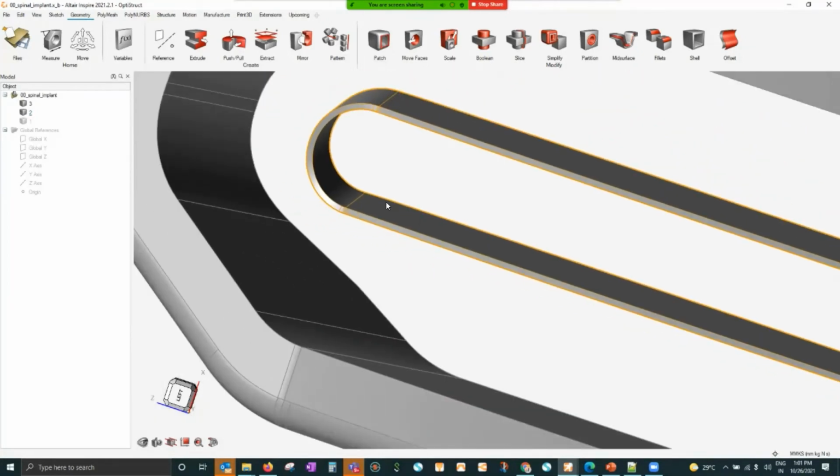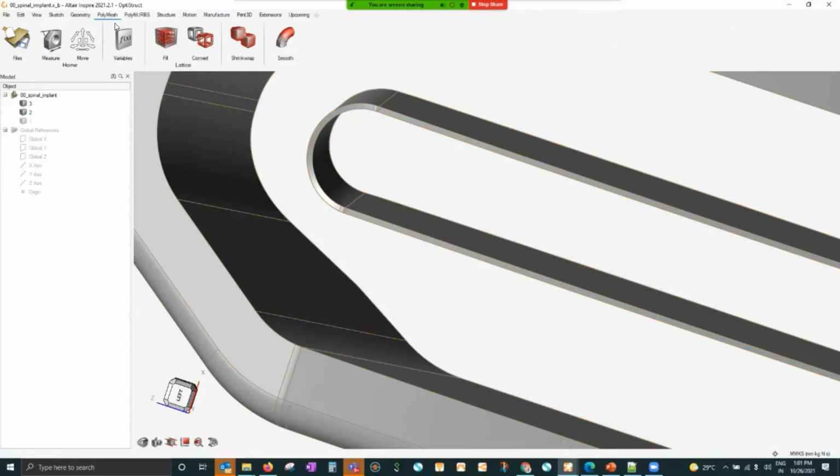That is number one. Number two is, if you don't want to do that, you can also play with the parameters of the lattice and make sure that the diameter of the lattice is smaller, in the order of this thickness. It is essentially the diameter which will cross. If you make the radius of the lattice in the order of the wall thickness, it will not cross. So there are two ways you can do that. Another way people do is that after they convert it into CAD, they boolean it. They chop those extra lattices and delete those things. That can also be done.